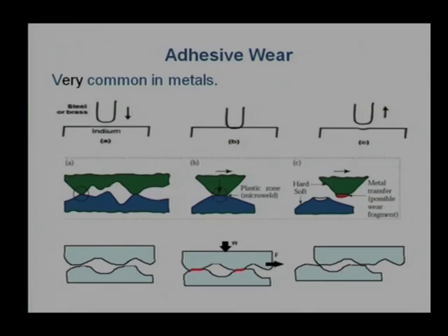Take an example of severe wear. See asperities coming into contact, undergoing plastic deformation, and what we call a micro weld. Now, if we push it with a tangential force, there is a possibility of junction growth and plucking out material, a blue color material here.